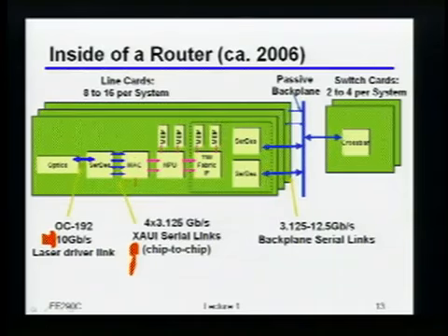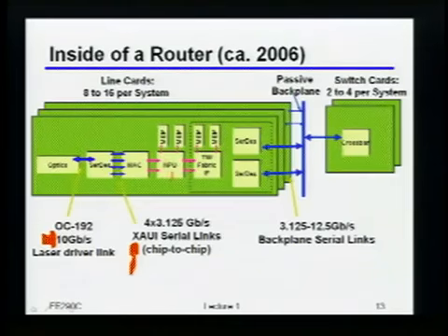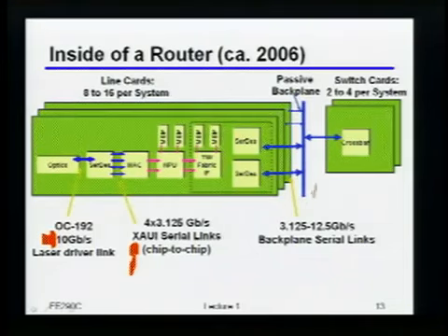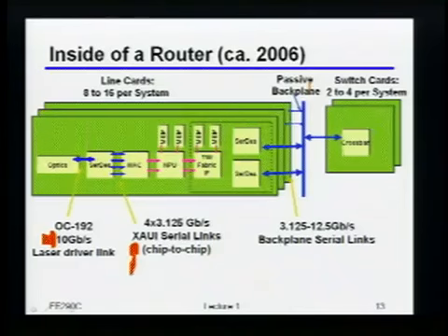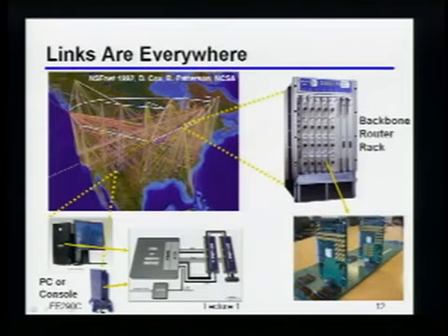From there, you have to do all kinds of media access processing, do the network processing, figure out where these bits are actually supposed to go, what's the actual other line card or switch card that I want to talk to, and then from there, essentially, you go out into what's called this passive backplane. Okay. So the passive backplane, that's just this sort of big board sitting over here. Literally all it's doing is it's a whole bunch of wires connecting these different switch cards to each other, or these different line cards to each other, okay?